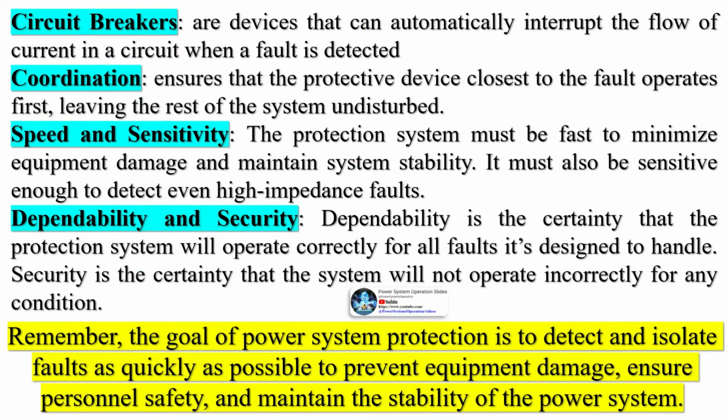Circuit breakers are devices that can automatically interrupt the flow of current in a circuit when a fault is detected. Coordination ensures that the protective device closest to the fault operates first, leaving the rest of the system undisturbed.